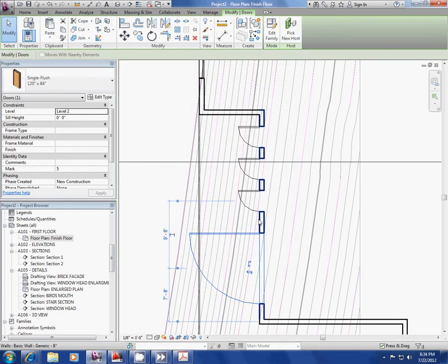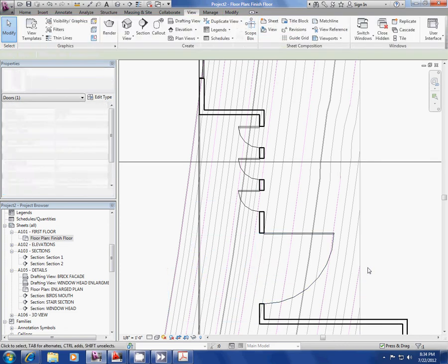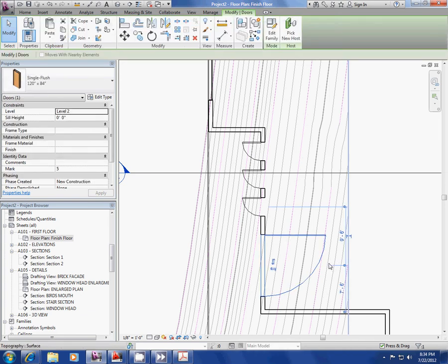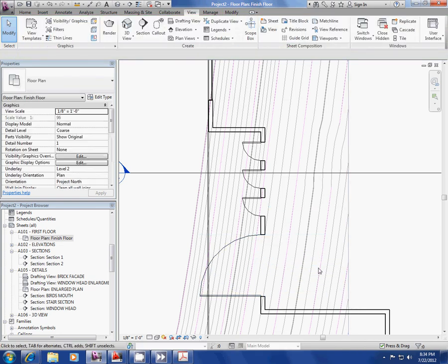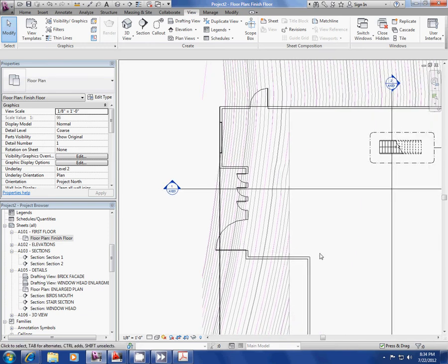You can see how that works when you click those. These symbols here toggle the swing and the orientation of the door. And that same command also works if you press space. So that really works with most of the common components, so doors and windows.